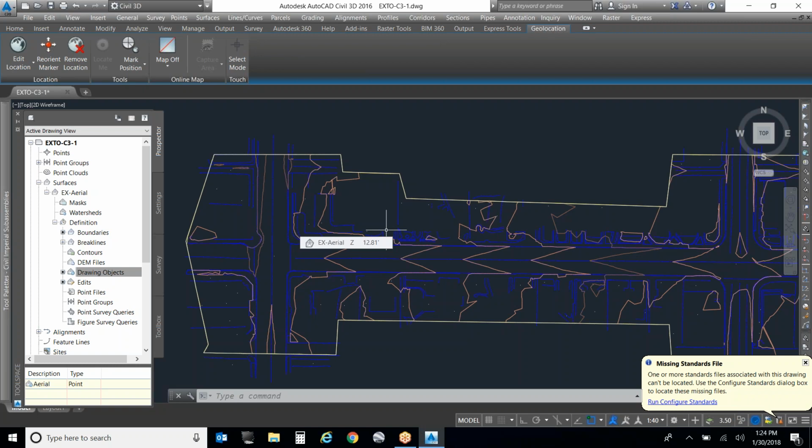Would we use this surface to do street rehabilitation plans? No. No, right? Why? This is level 1 accuracy. Level 1 accuracy in terms of where this data came from, right? Came from an aerial. We need a design off of the highest level, which is survey data, either GPS or total station. Right? So what happened in the payout of part of that $100,000 is they designed from this aerial data. Even though the surface looks good, it's bad information.